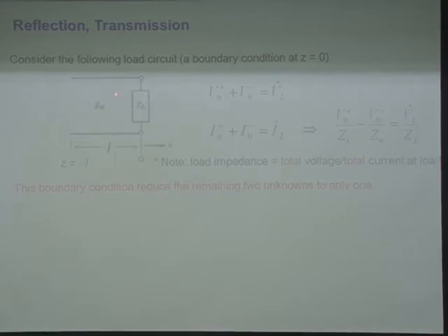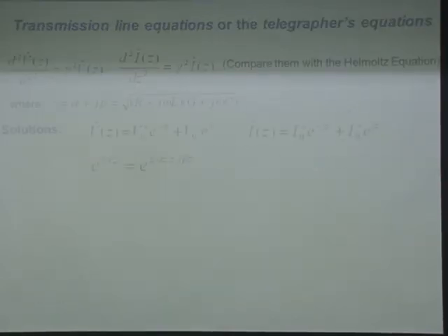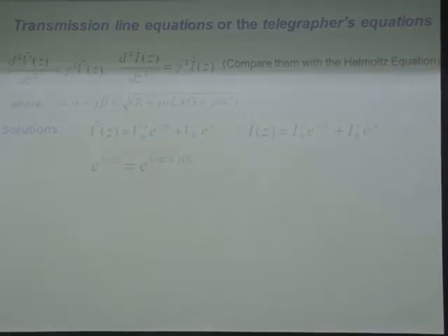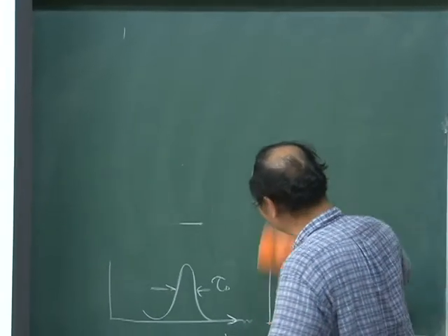At this point you have a forward-traveling wave and a backward-traveling wave, so you have V0+ and V0-. The same thing, you write down the same expression for I0+ and I0-. Where is the z equals 0 point in this design? Here. Let's denote the origin of z at this location. If I go back to the solution right here, I'm setting z equal to 0 in that expression.